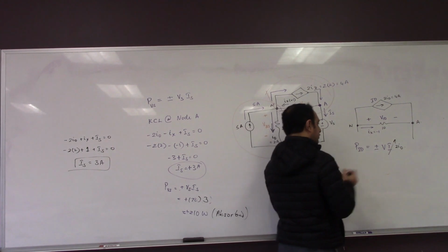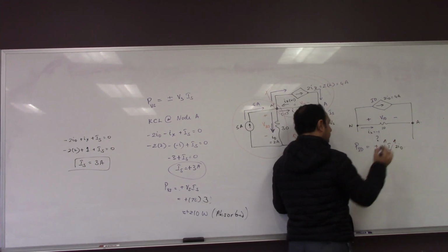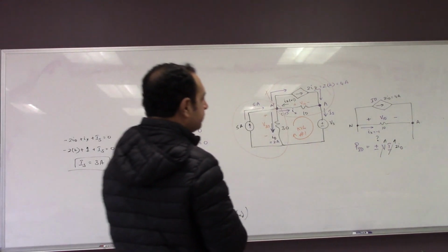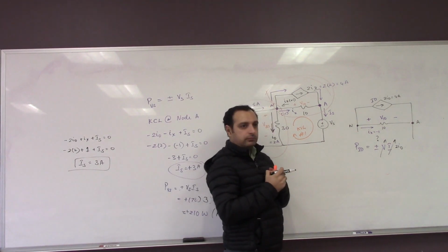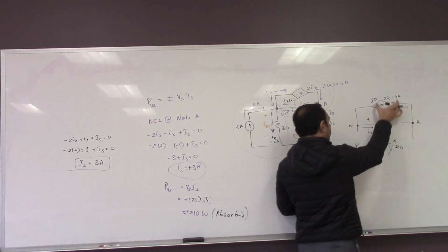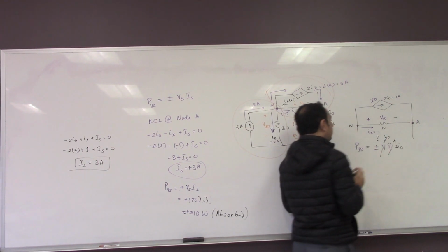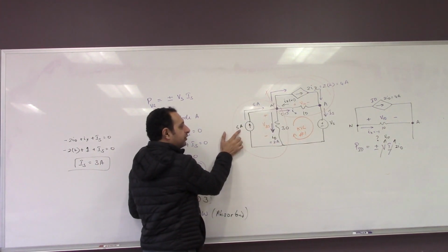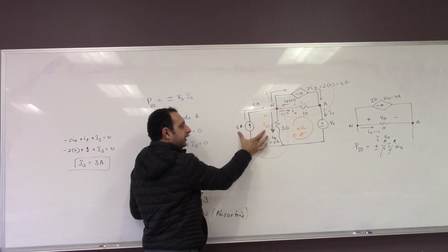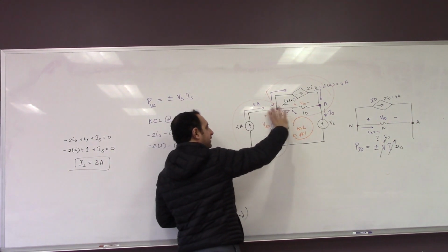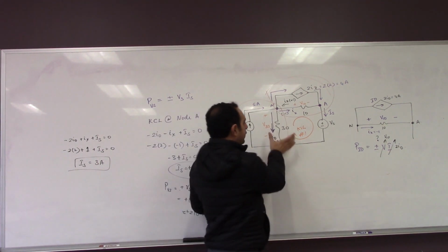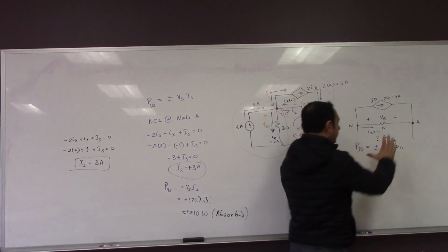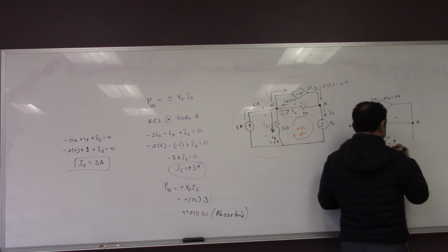How about the voltage? What is the voltage across the source? V10, exactly. They are in parallel, so this is V10. So V10 is the voltage across the source. Same concept here, when you're doing this source, the voltage across will be V30, because they are in parallel, so you will apply exactly the same voltage across this. All you have to do is look for a parallel element whenever you have a current source to take that voltage.